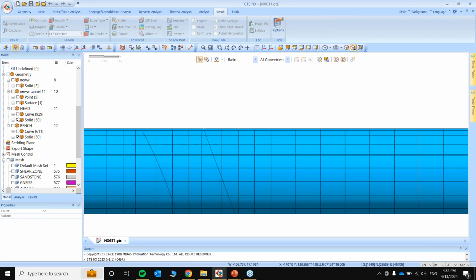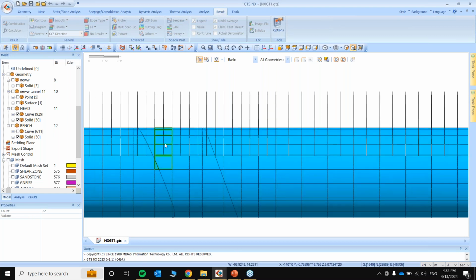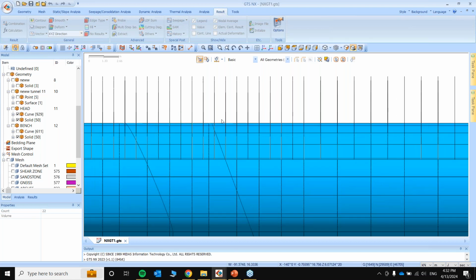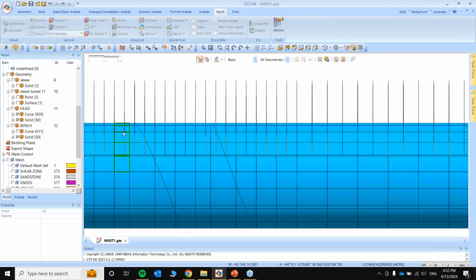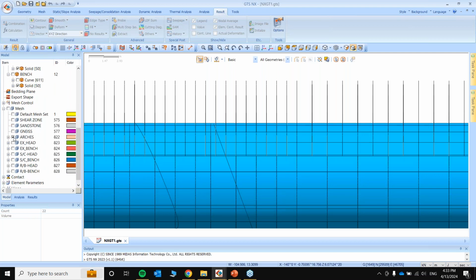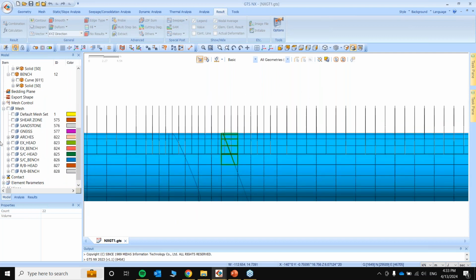I had mentioned that we had an extra amount of rock bolts in this particular part. So if I just show you the rock bolts near the shear zone, you can see each roof is having one extra pair of rock bolts, or extra system of rock bolts. And apart from that, we also have steel arches in this part.